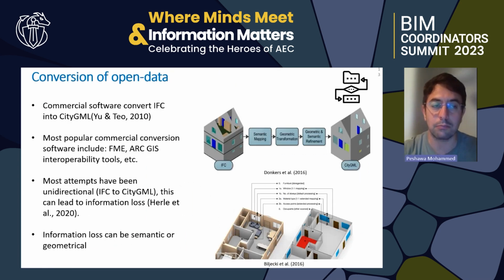Regarding conversion, it's mostly done using commercial software. Most popular ones are FME or ArcGIS, the ArcGIS interoperability tools. However, it's worth noting that most attempts are unidirectional. It means from IFC to CityGML, and this can lead to information loss. And this information loss can be semantic or geometrical.